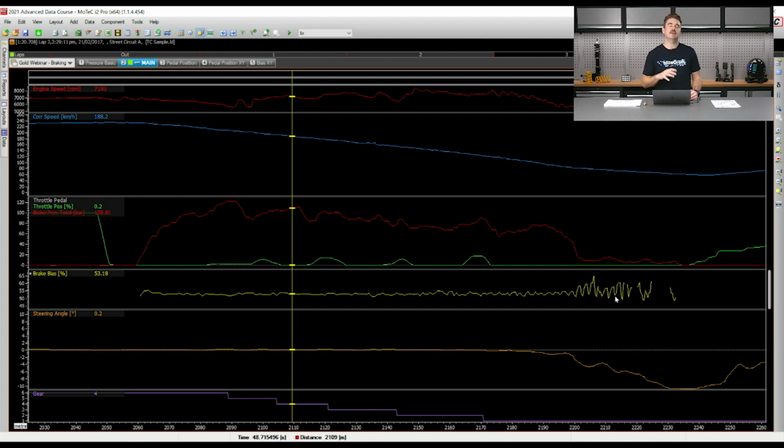The idea is that it adds a little bit of dynamic rear brake bias just when you're releasing the brakes. Obviously, when you're releasing the brakes, this is the time when you start to rotate the car into the corner. So for some cars that can be a big advantage when you add some rear bias on corner entry, if you're struggling with understeer in the first place.